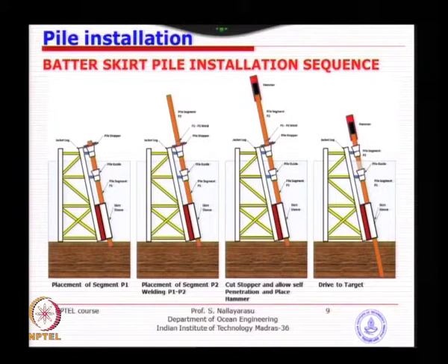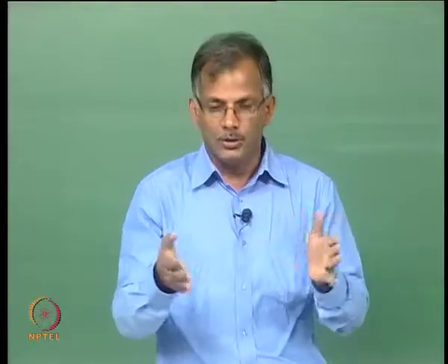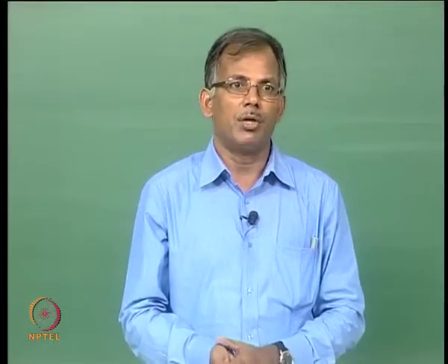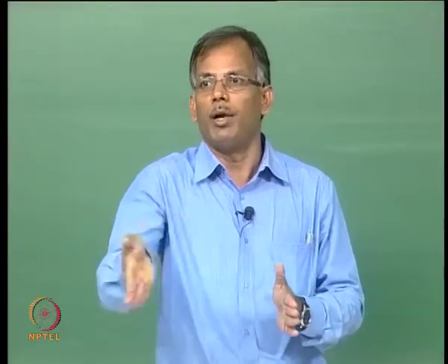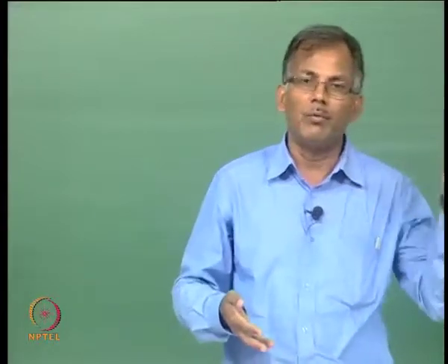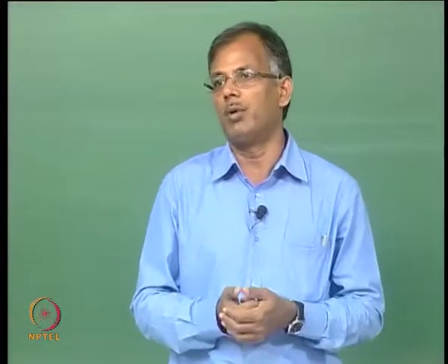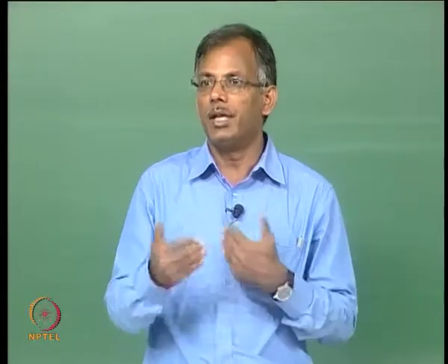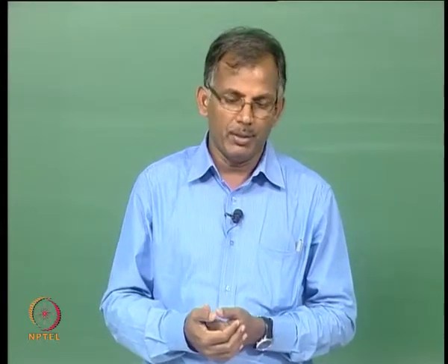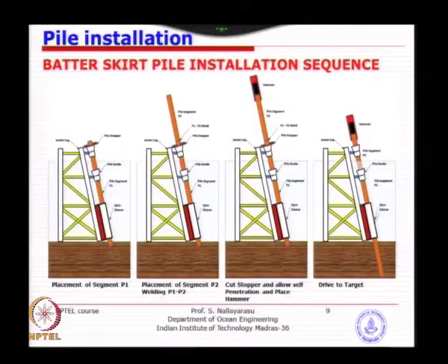If you have designed for such a scenario, we call it pile driving sequencing. There is no harm in doing that, because this particular series sequence of going one by one will take 3 days, whereas the other one may take actually 2 days or 1.5 days. That means you can save a lot of time and money, but all that requires is design.